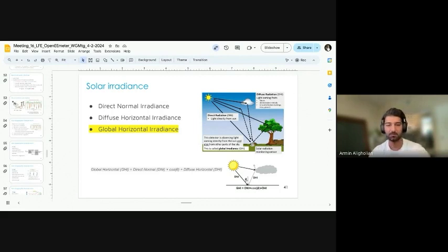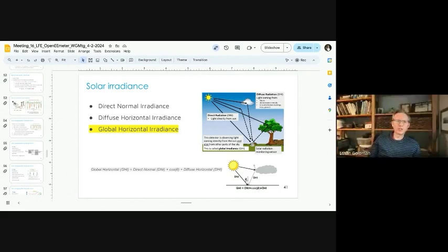Travis, well, the way to fake out the data is less about showing GHI pegging at 1,000 watts per meter squared arbitrarily, and more to just put a cap on your solar. If you had just solar data, just set that to a min of, say, take a 6 kW solar data set and say it's a min of 4 kW or the actual, and then you'd get a cosine with a ceiling on it, and that's what it would look like if you had an undersized inverter. But generally, yeah, we could make a fake data set. We could test this out.